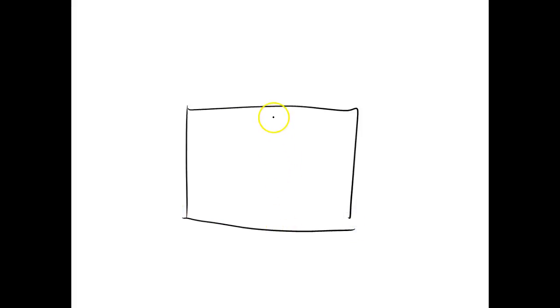Usually it'll have baffling in it, and it'll be a square, and then you'll have a baffle in the center. Your pump is going to be up in here or onto the side somewhere. And what we want it to do is create suction on this side and then shoot it down toward the bottom. Then your return will come in here.